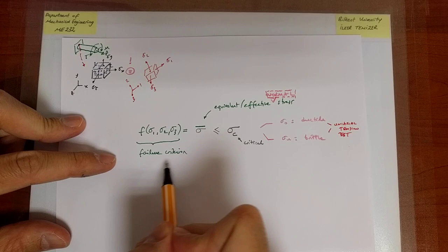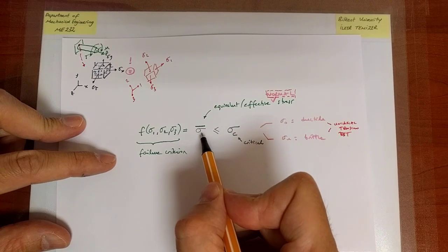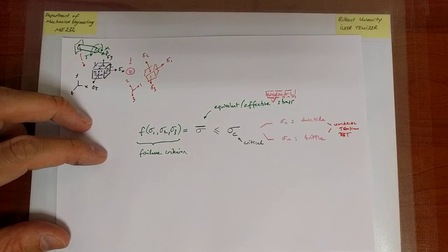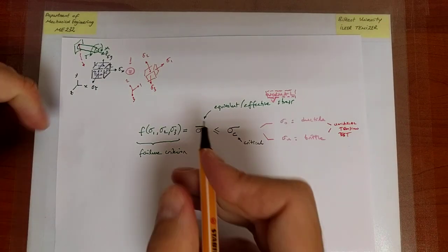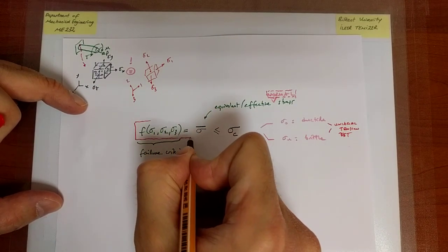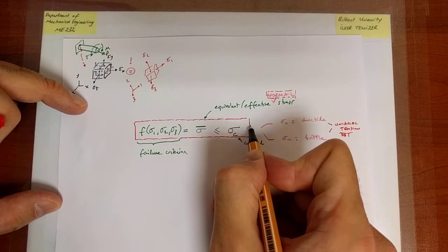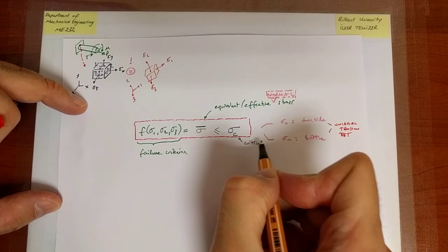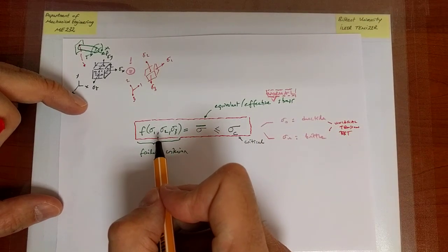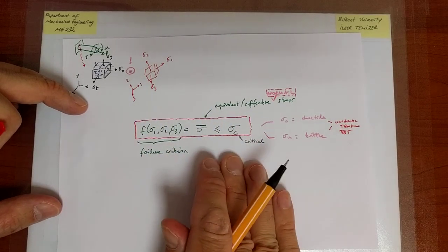So the criterion will take that complicated state of stress, convert it to an equivalent effective normal loading, and then compare it against the critical value that comes from a test where the loading is exactly in that form. So this, therefore, is going to be our, if you like, stencil. And we should remember this stencil, and we should remember the ideas that go into the stencil. In particular, we should remember that the critical value is a value that's associated with the uniaxial tension test, and therefore that if this state of stress is actually a uniaxial tension test, it should still be satisfied.